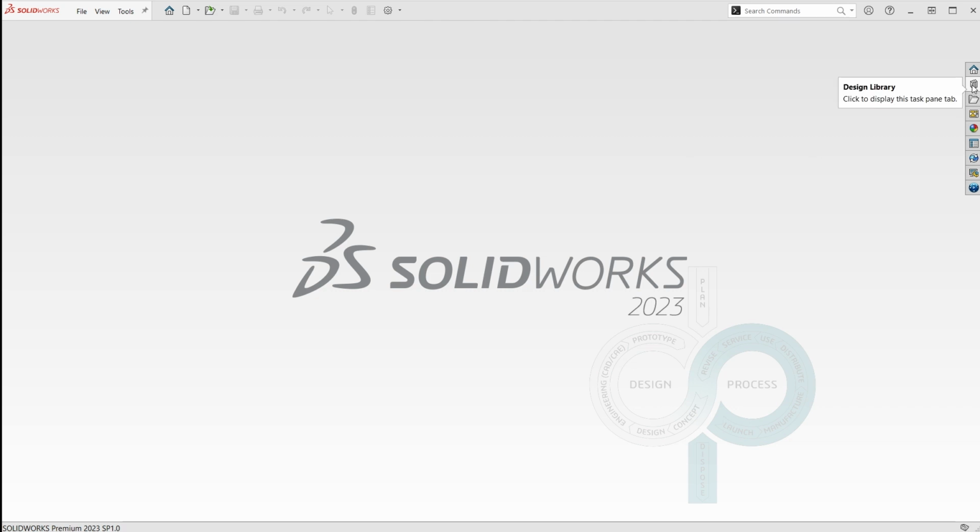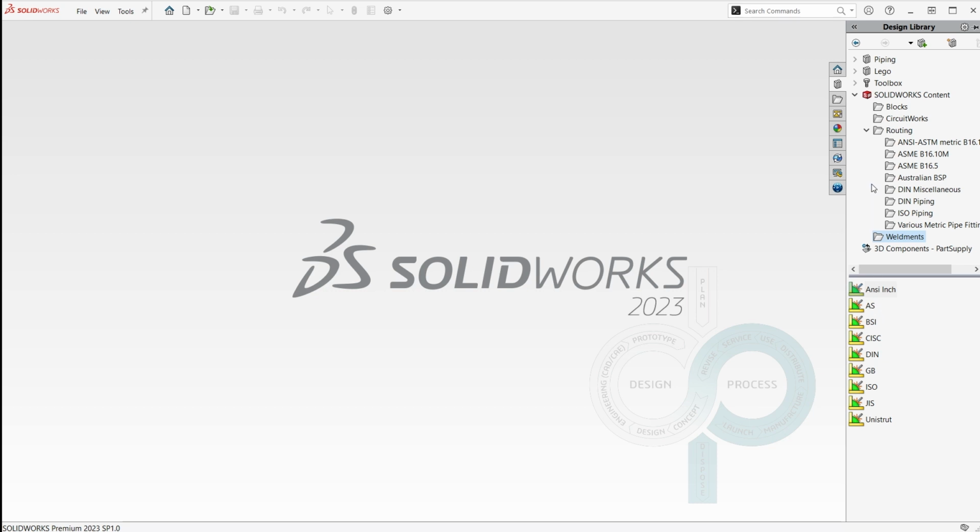I'm going to come over here to my Design Library tab, and if you pick here underneath the SOLIDWORKS content and come down to weldments, you'll notice that there's a bunch of weldment symbols here. You can see we've got ANSI inch, we've got ISO, we've got Great Britain, which is also used a lot for Chinese structures. And then we've also got Unistrut, Japanese standards, etc. So for us today, we're just going to copy the one unit, which is the ANSI inch.